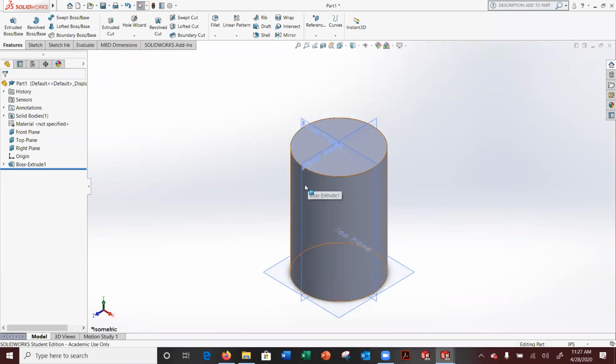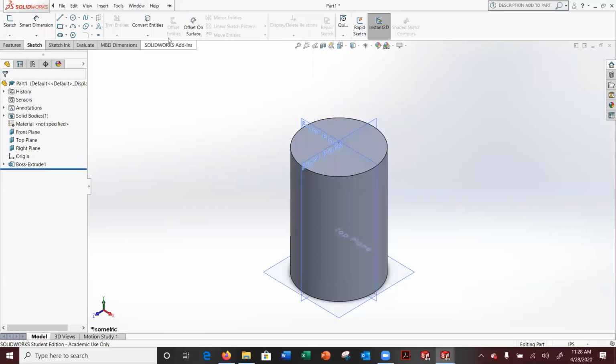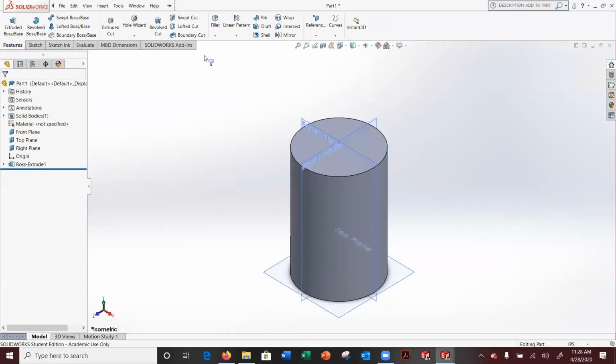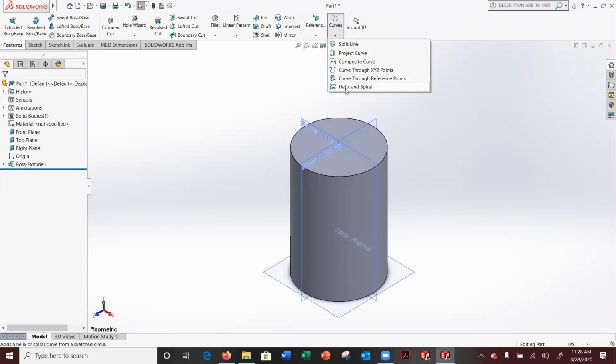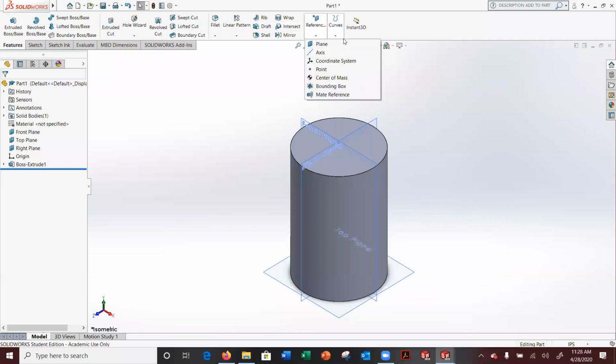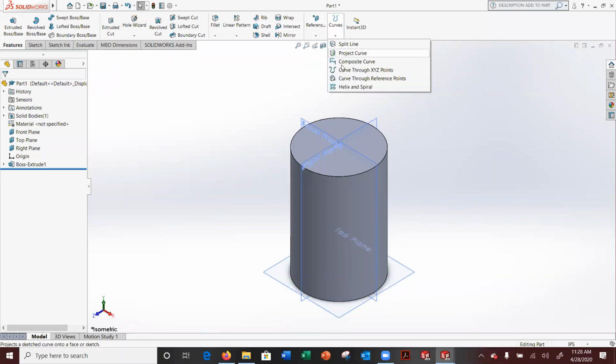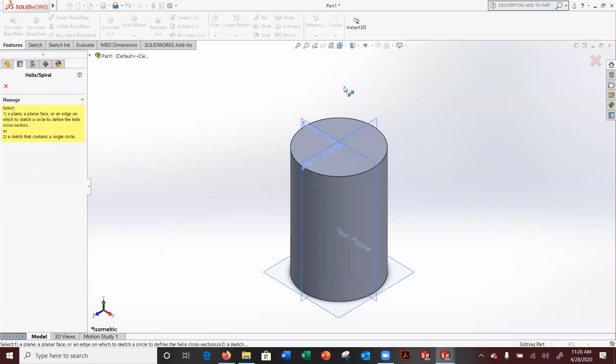The first step in creating a thread is identifying the sweep, the pattern that's going to be used to make the thread. So the best way to do that is to go into Sketch. If I'm going to do that, not actually Sketch, but go into Features and the Curves reference, where you have to create a sketch of a helical pattern, okay? Again, that's under Features. After References is called Curves, and you're picking Helix, okay?